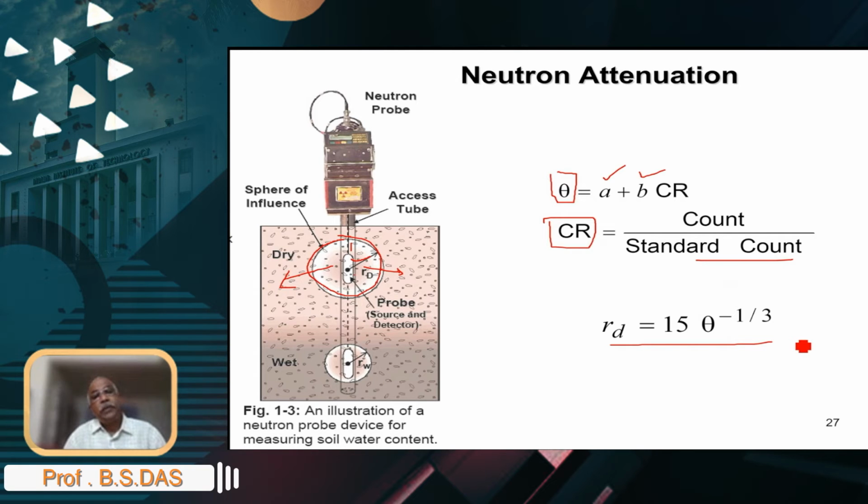And so with a very wet soil, typically you are going to see that your volume of measurement is small. So you are measuring water content in a smaller volume, whereas in a dry soil you are measuring in a larger volume of measurement, and that really gives you uncertainty about where you really measured water content. That's one part of it.